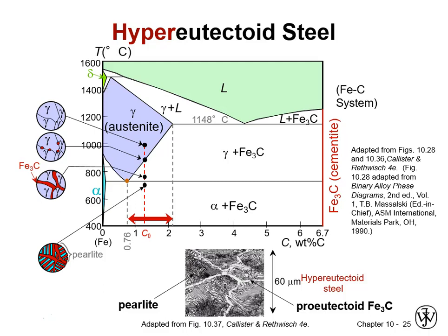And so you can see from here we don't have a lot of primary cementite relative to the amount of austenite prior to eutectoid transformation. So we've got a relatively thin layer of that continuous brittle cementite, which is good. Otherwise this would not be a fracture tough alloy. So much more pearlite than cementite in this case.